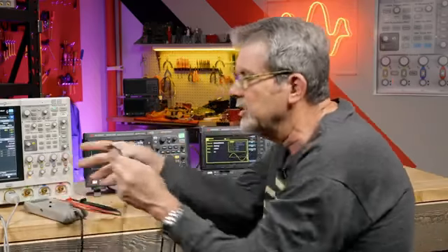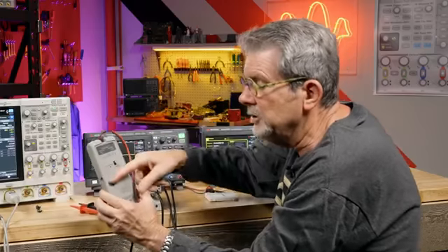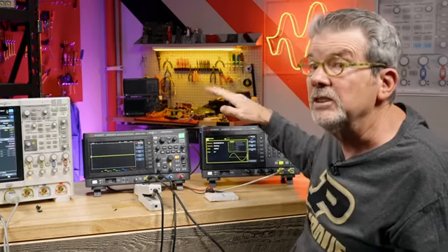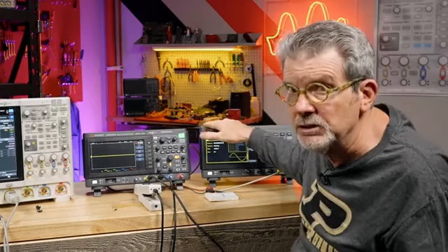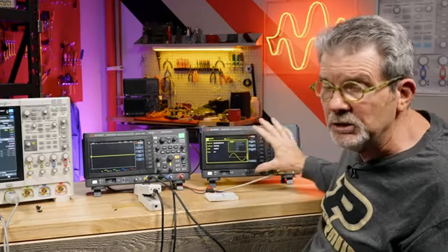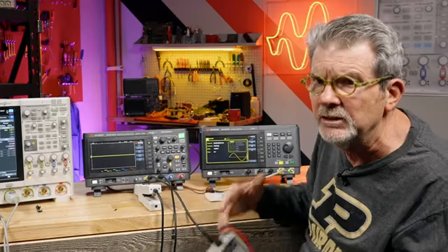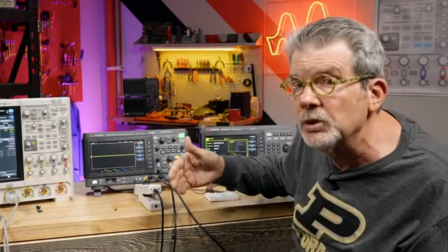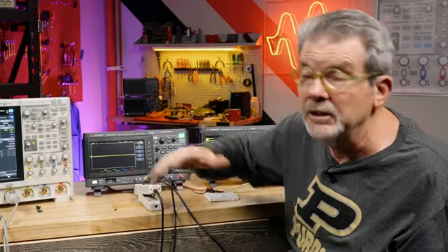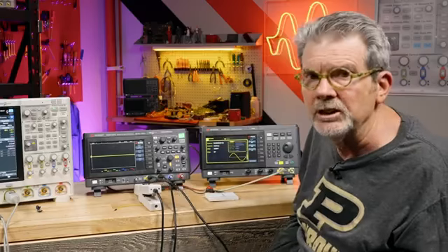And let's also connect up our high voltage probe and turn this one on. And what we're going to measure is the input AC voltage to this function generator. It has nothing to do with what the generator is generating. Just think of this as any system or any DUT. And we're going to measure the input voltage and the input current. And ultimately, in the lesson after this, we're going to measure the power consumption of this particular instrument here.